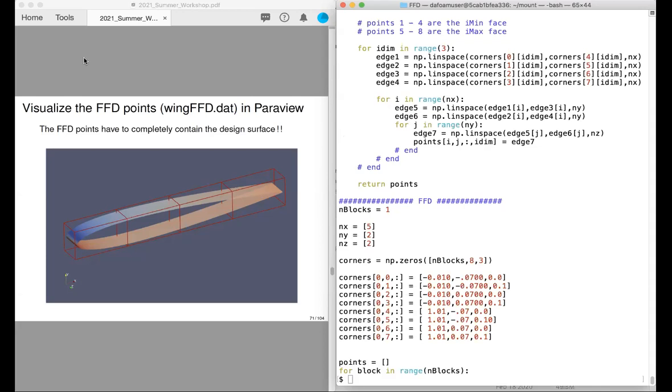Okay, so given the fact that for whatever reason, I want to optimize only the frontmost 50% of the airfoil, I would define basically 4 patches, like the rear, the aft end, and the front end. I would separate my mesh into front and back, and then enclose only the front part, and then it will run smoothly. That's right. So that's one way to do it.